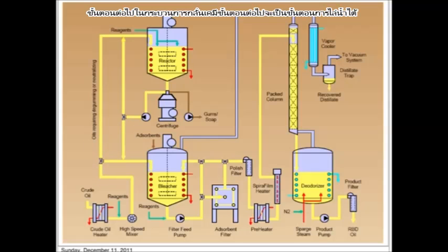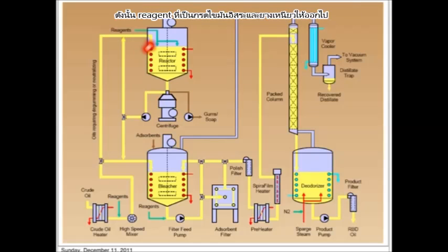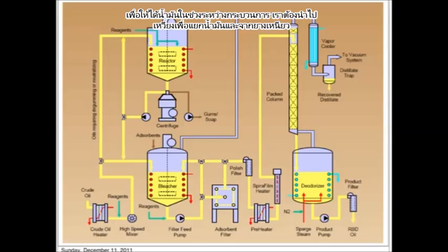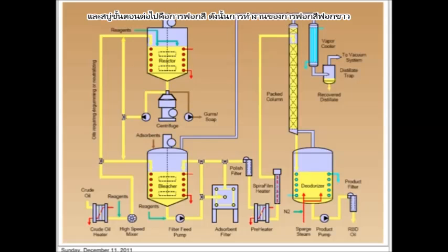In a chemical refining process, the next step would be the neutralization process, where sodium hydroxide, the alkali, will be added, and this will react with the free fatty acids, and the gums will be formed here. So we have the oil and the gums together formed during the neutralization process. We need the centrifuge to separate the oil from the gums or from the soap.